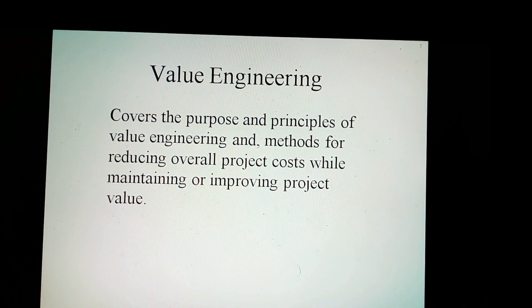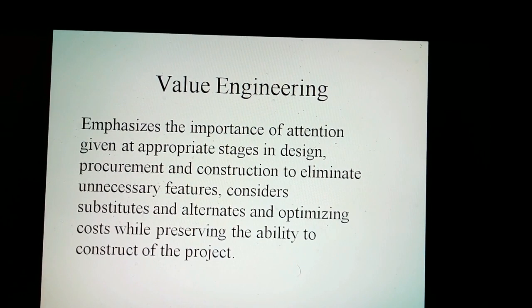Value engineering. It covers the purpose and principles of value engineering and methods for reducing overall project costs while maintaining or improving project value. It emphasizes the importance of attention given at appropriate stages in design, procurement and construction to eliminate unnecessary features, considers substitutes and alternates and optimizing costs while preserving the ability to construct the project.